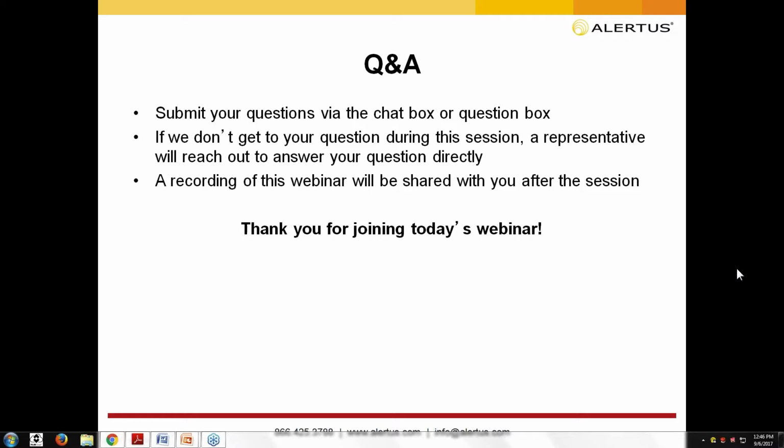Great. As alerts are triggered on the fire panel, how do you control and filter which alerts will be integrated with Alertus? Sure, that's a great question. Anytime that the fire panel provides its code, it will provide either a label of alarm or fire. It really depends on the manufacturer. They all have different uses. So it could either be fire or alarm as the first label. It could be a supervisory condition. It could be a trouble condition. It can be just a reset of the fire panel that we demonstrated earlier.